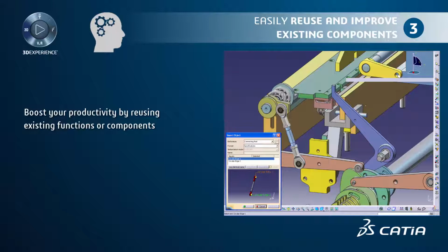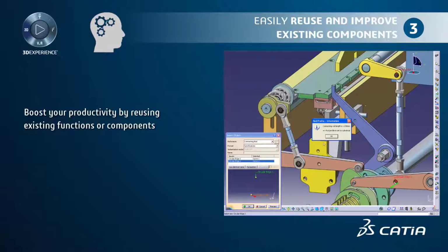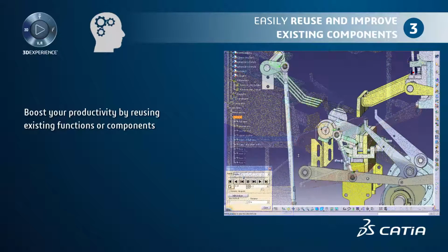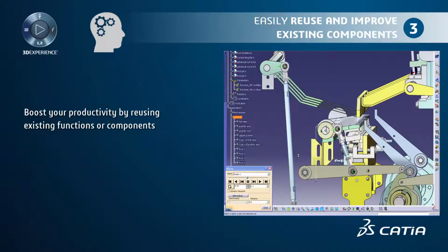An embedded design rule automatically chooses the rod profile depending on the rod length. For the second generated rod, the rod profile is automatically set to a circular one since the rod length is above a specific value defined in the rule.